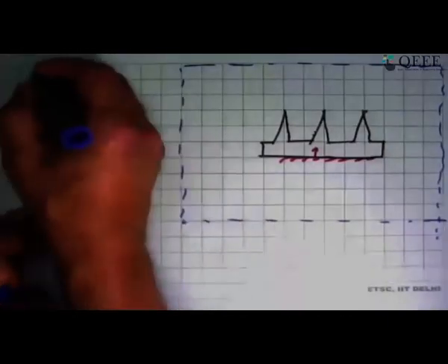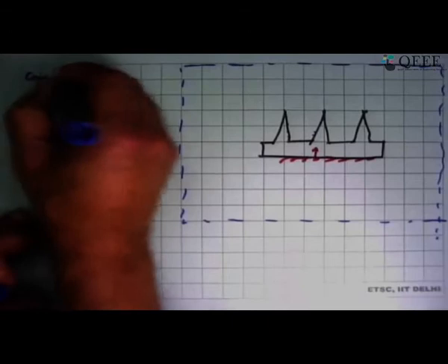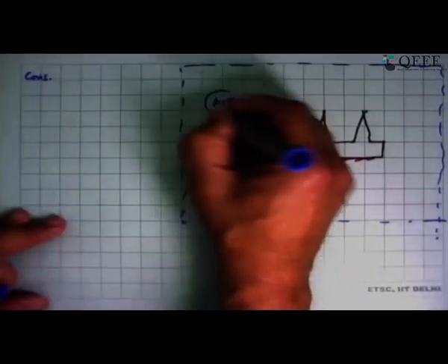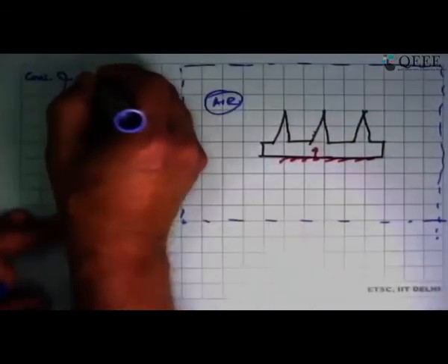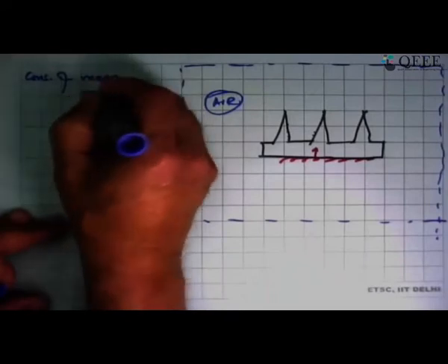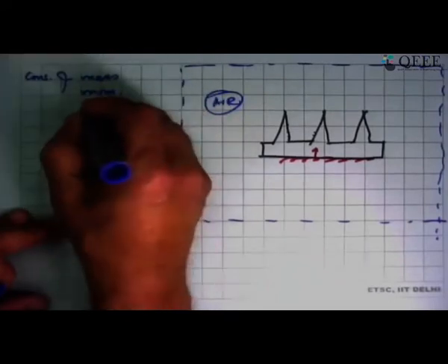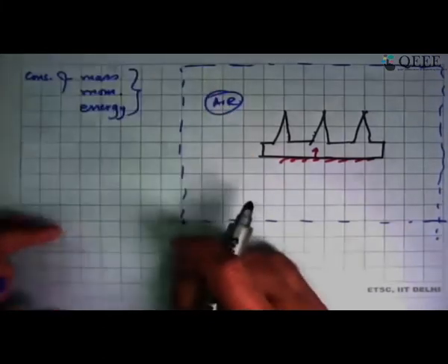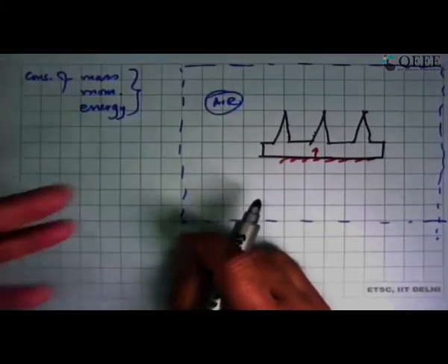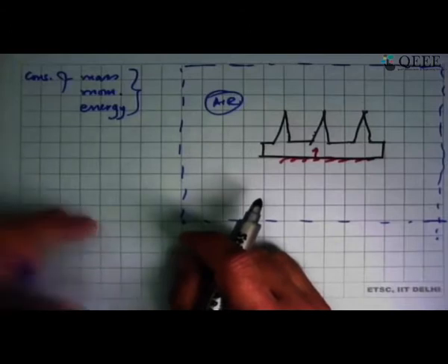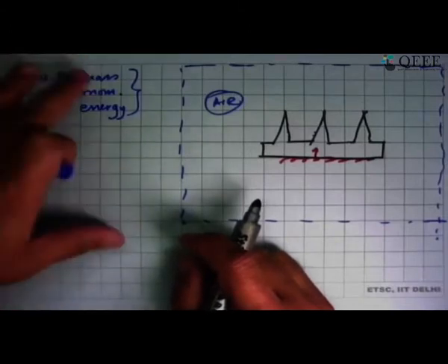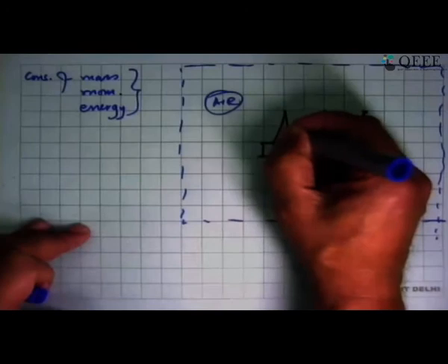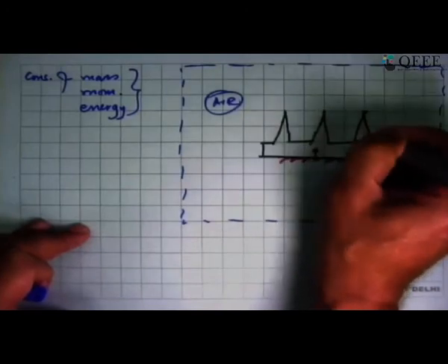So the equations that we write, first is for the air now, conservation of mass, then the conservation of momentum, which is a vector, and finally conservation of energy. Three equations we need to solve simultaneously, we get the velocity field everywhere. So if we are good enough in solving it, and we say that look, everywhere here the temperature is the same, and how much heat transfer will that be? In that case,